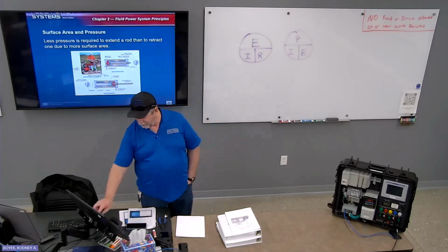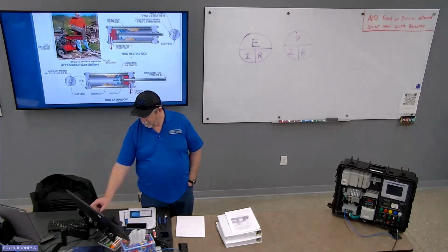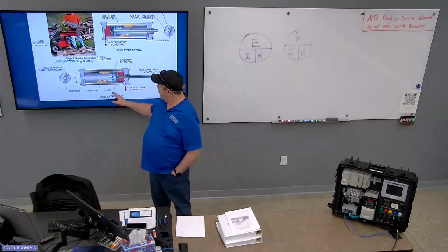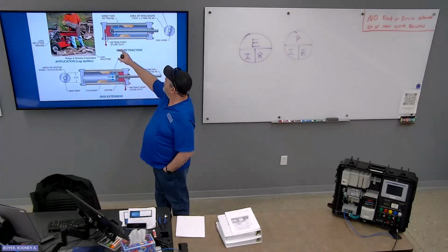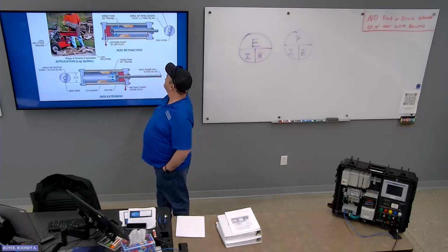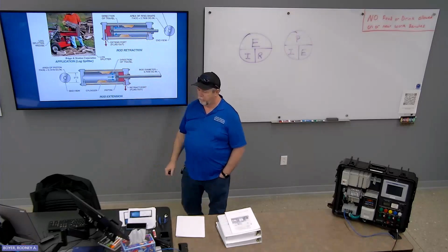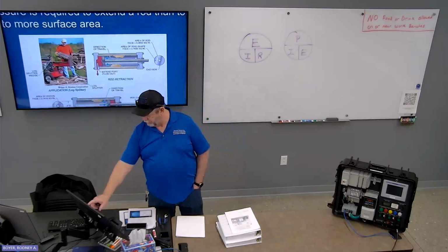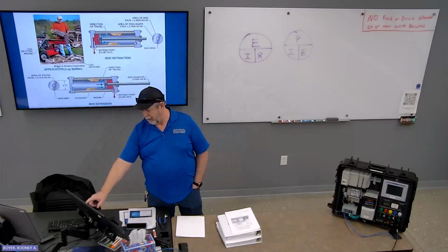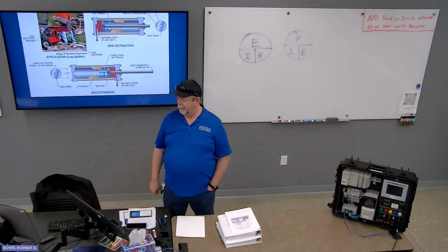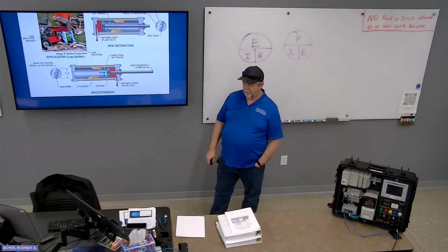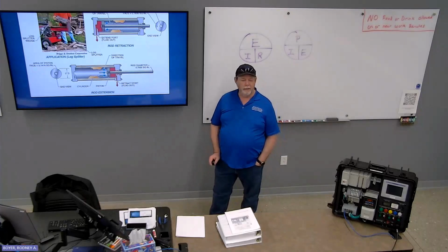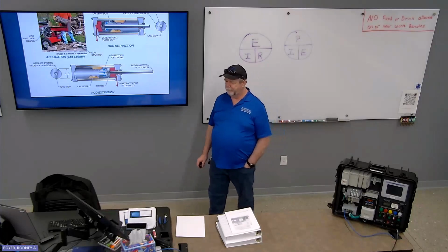Like I said earlier, you've got the full 2-inch bore there, and then you have a 2-inch minus whatever the diameter is, a shade over 3/8 of an inch for the rod in that case. You have to subtract that area, not just the diameter, but the area of that from the effective area.